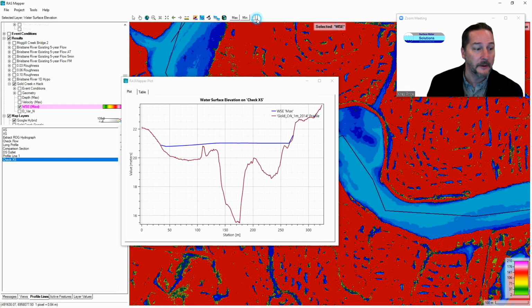So here it is. If I come in from 0 as the storm starts arriving and I've got some of this sheet flow, again, think about how this happens over time. You might have a different roughness value here at this time step than you would up at this time step. So maybe we ought to have true depth varying roughness over the entire hydrograph. So this is more helpful.